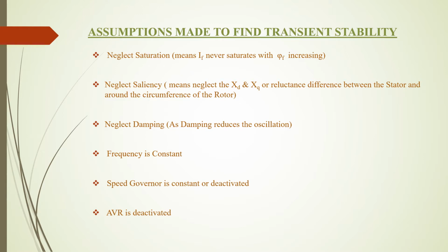As we all know, damping reduces the oscillations. The fourth assumption is that frequency is constant. And the fifth most important assumption we need to make is that the speed governor is constant or deactivated, and the final one is that the AVR is deactivated.